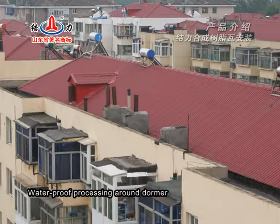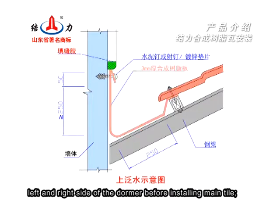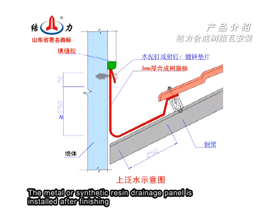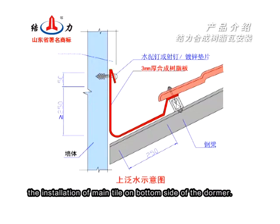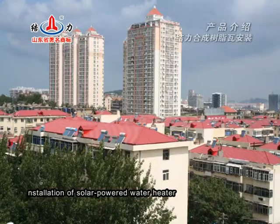Waterproof processing around the dormer. The metal or synthetic resin drainage panel should be fixed on the top, left and right side of the dormer before installing main tile. The metal or synthetic resin drainage panel is installed after finishing the installation of main tile on the bottom side of the dormer.